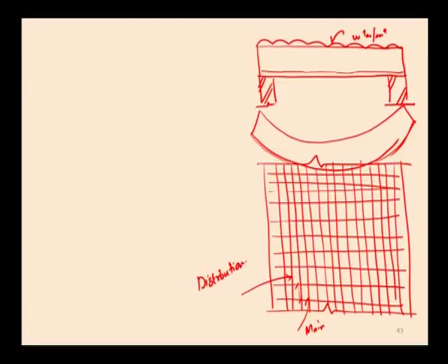This distribution reinforcement is not only to distribute the main reinforcement with proper spacing, it is also to avoid the cracks which develop due to shrinkage and temperature variation. This normally develops in the long term. So, this is the arrangement of reinforcement in the case of a pure simply supported slab.